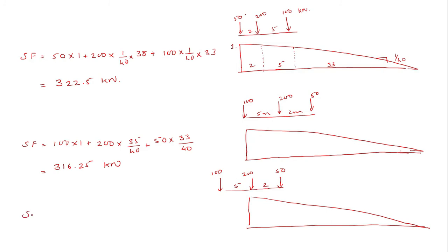In that case, the shear force will be equal to 200 into 1 plus 50 into 38 by 40. So you get a value of 247.5 kilonewton.